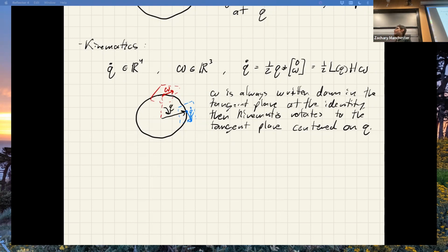That's the definition. I can write it as a rotation matrix, as a quaternion, or, if I'm a sadist, as Euler angles. That's it. If I took a vector in the body frame, say a camera boresight or my angular velocity from my IMU, these are all defined in the body frame. If I wanted to know what it was in the world frame, I would rotate it by my quaternion or rotation matrix that defines my attitude.